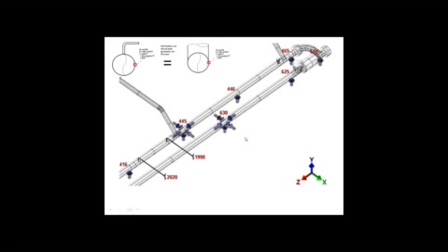What you see here is a small D over D ratio. When we get very, very small D over D ratios, WRC 329 says these SIFs in the run are obviously silly. What B31.3 and B31.1 do is shown at the top. The top left image is what you have: a very small bore branch connection.